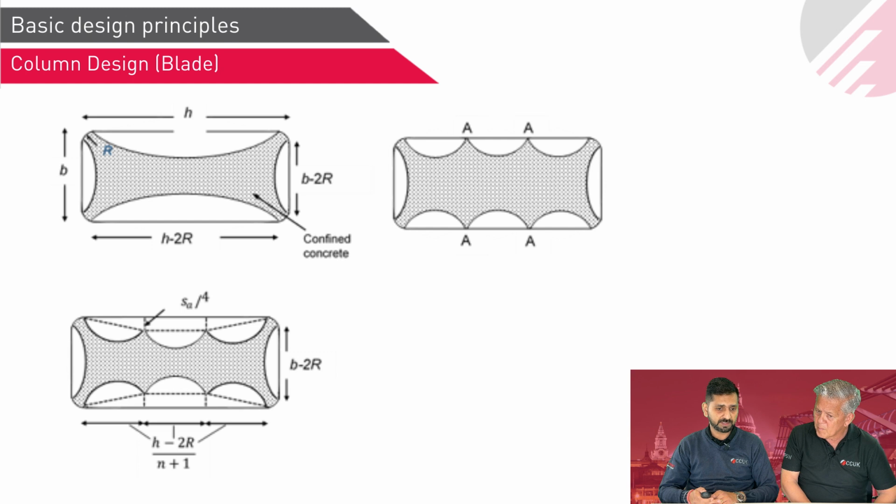In this slide, the top left image shows the column without these anchors. The stress concentration is in the corners, where it shows a reaction, R. It pushes outwards, which means the confinement on the longer side will not be that effective. To change that behavior, we could use carbon fiber anchors as ties.